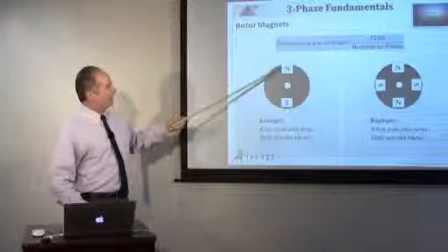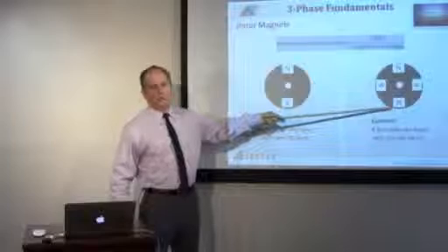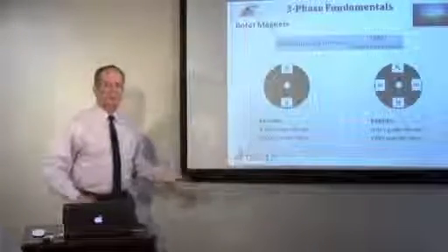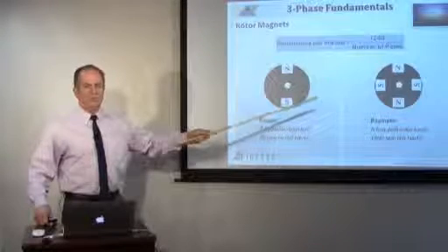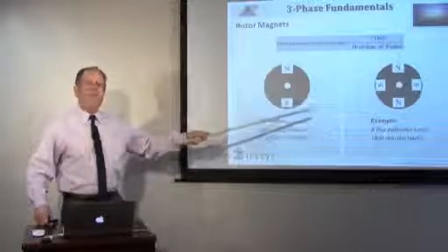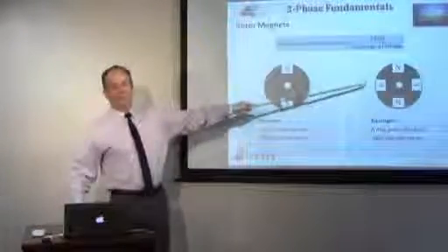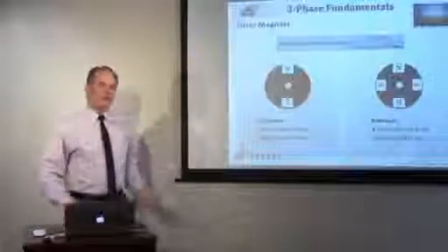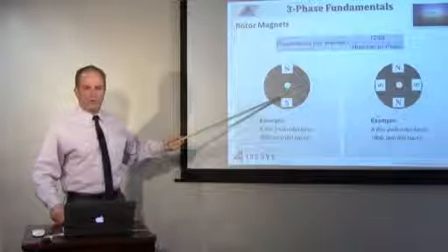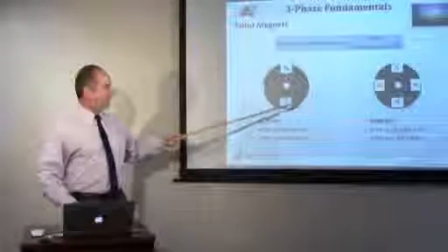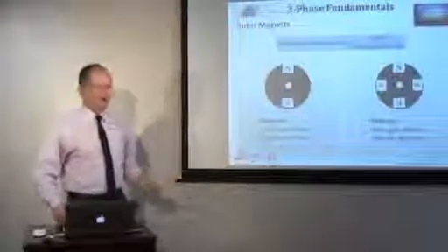So if we had coils of wire, we could increase the number of coils so that we can have multiple coils on a rotor and cause the rotor to only have to spin half as fast, in this case where we have 4 poles. If we have a 2-pole rotor, our generator normally spins 3,600 RPM. If we have a 4-pole rotor, it will now spin 1,800 RPM.